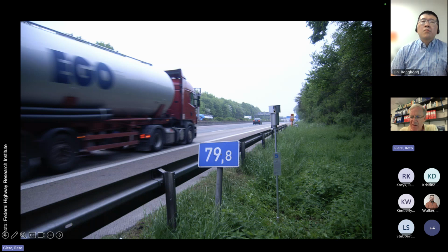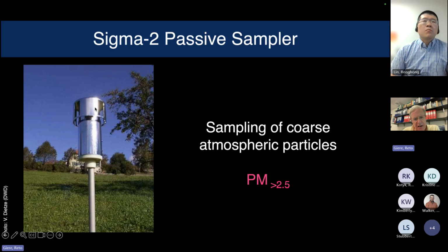It's a laminar flow in here, very quiet environment. And then the particles settle, according to Stokes' law, on a collecting plate. And this is how we get access to it. So this is a little bit in more detail.